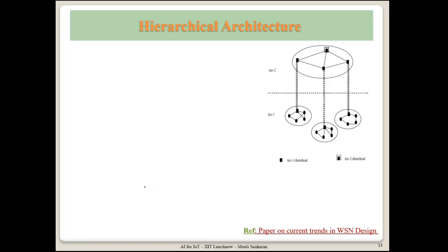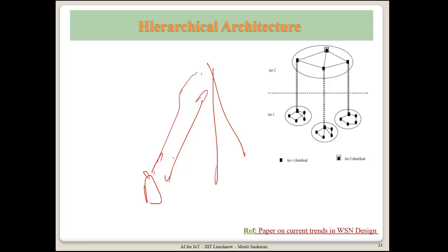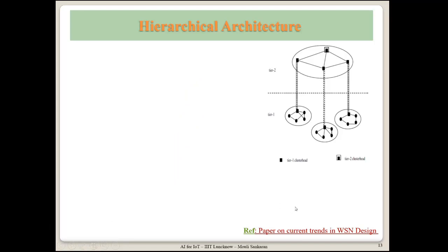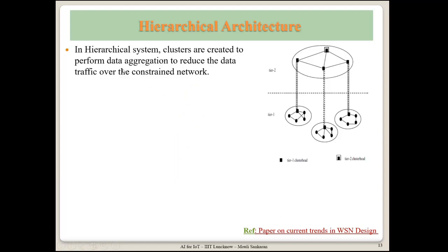Suppose your mobile device is very close to the tower; it doesn't radiate very high power to the tower. Because it finds out the distance between the BTS and the mobile, and radiates only what is needed. That kind of optimization is done by the radio. So our battery is saved because of that, and this kind of optimization is naturally done in WSN.